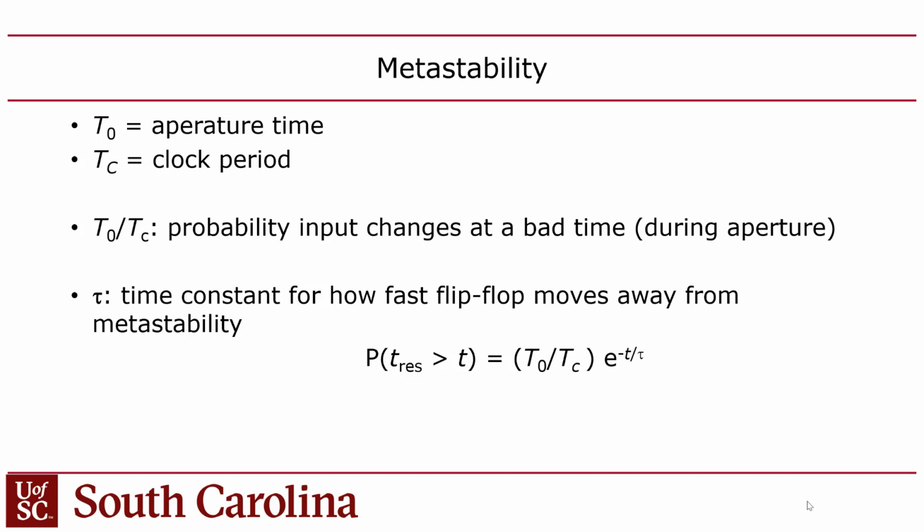But how does increasing chip area help improve the speed characteristics of the holes in the chip? It doesn't. If you make the PMOSs bigger, or if you make all the transistors bigger, you can improve the discharge rate. You can strengthen the drive of the gate, right? But you still have that fundamental difference between the N and the PMOS. That's the problem. Hopefully I explained that right.